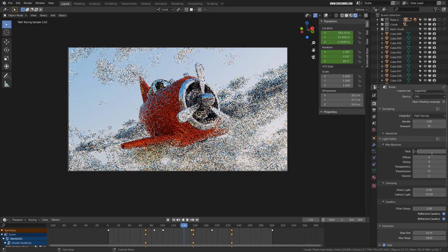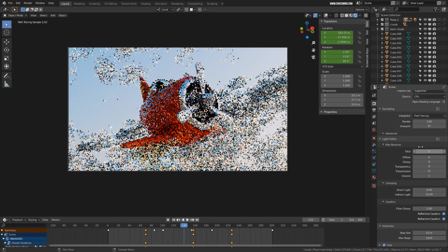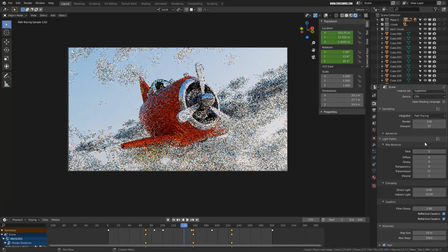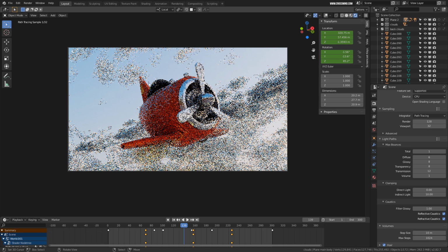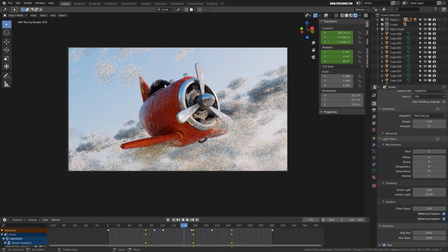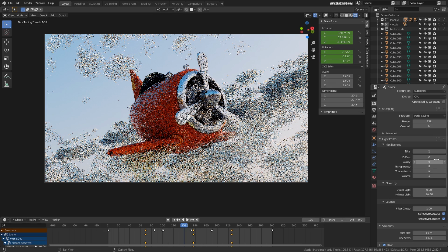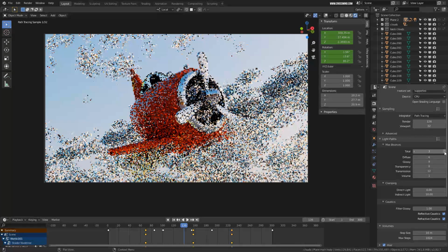So I'm going to put a very drastic number over here. Let's make it 5 for now, and see how much it's affecting my render. Now if you see, if I make this one 1, you'll see some of these things start to look really flat. Because of 1 in transparency, what is happening is, because we have 4 walls, outer and inner, this glass is starting to look black. So 1 will not work, so let's make it 2, 3.